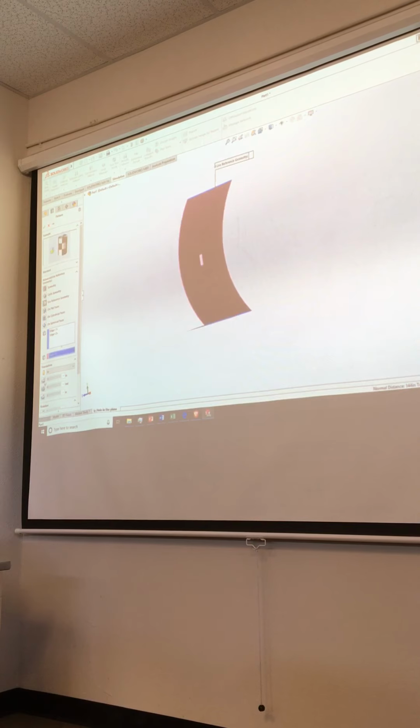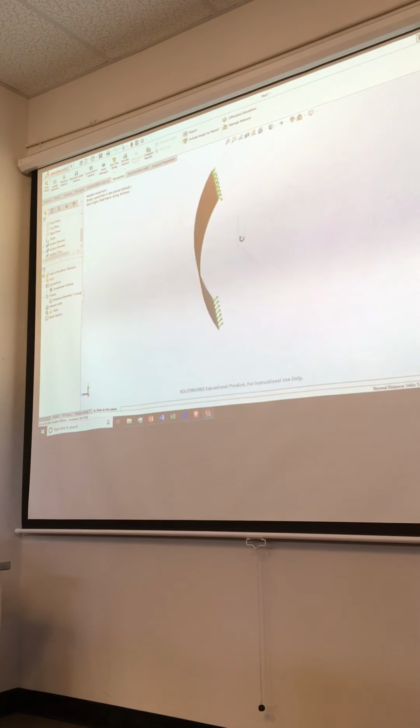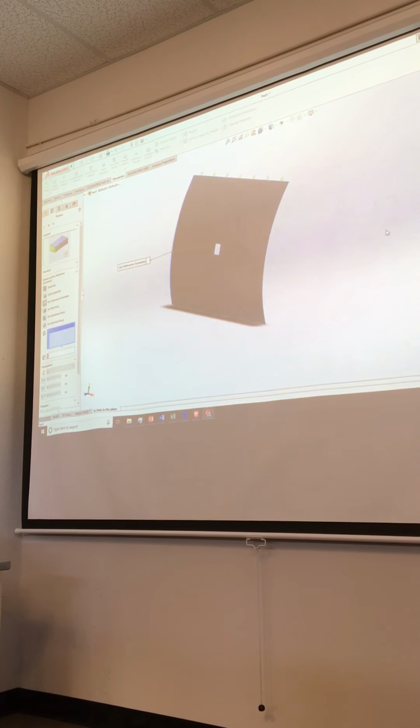So we're going to fix it to where it can't move in the radial direction. That's part of the boundary conditions, and we're going to fix the other rotations, the orthogonal rotations. Okay, let's get that one. Right. And now what? Well, let's do it again, right? So let's pick that guy there, and this one over here too, right?